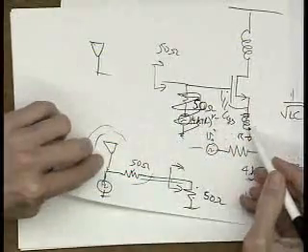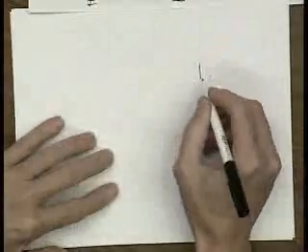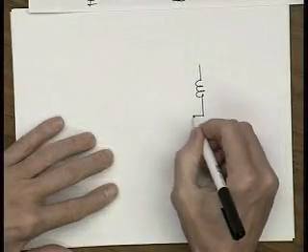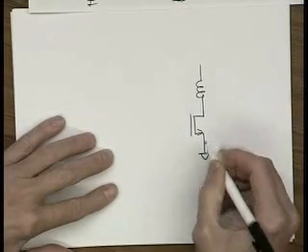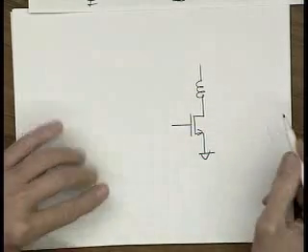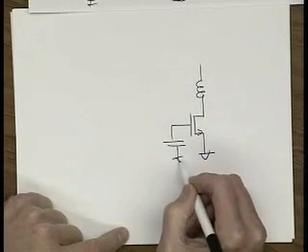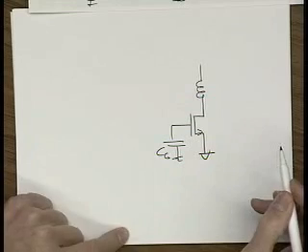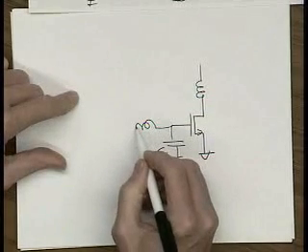And you don't have to put a resistor here. So it's actually a noiseless way to make this look like 50 ohms, okay? That's pretty neat. So let's take a common source stage, but let's not put this inductor down here because that's your homework problem. But let's do something else. Let's talk about how you analyze these circuits, okay? And it's just like we've been doing all year, right?